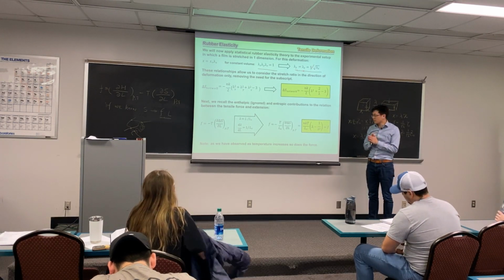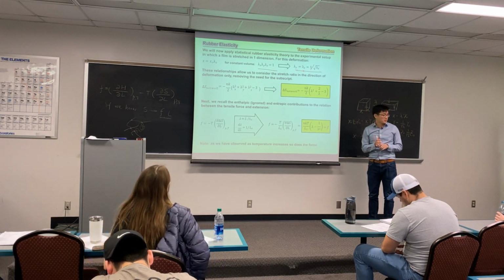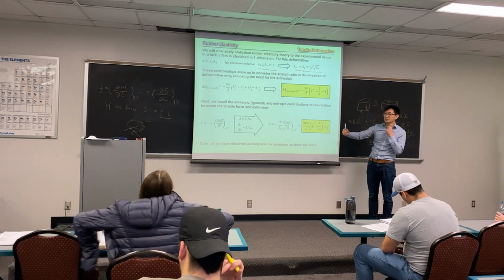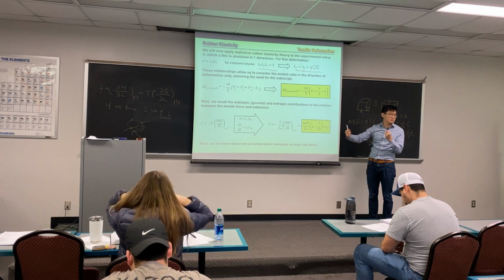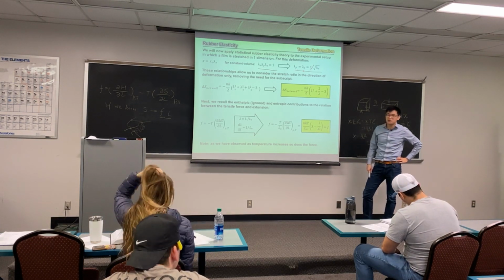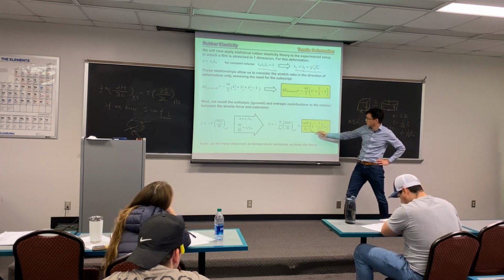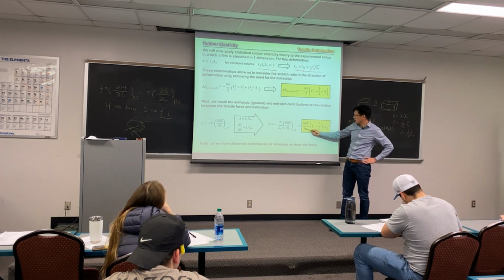a beautiful theory that describes how much force your polymer network would give you if you deform n strands of Gaussian coil in your elastomer. Force, let's see what it's proportional to. The force is proportional to L0, the initial length. It's a constant so it doesn't change.